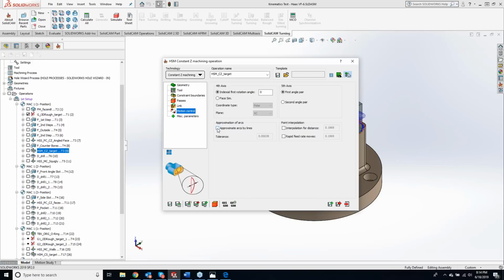So if we turn this on, we're going to get arc segments versus line segments. Kind of like what we're looking at with that iMachining picture, as you're doing surfacing, it's going to try to force arcs in there versus just little tiny line segments going through there. So you definitely have... I think you got that backwards, Kevin. Oh, that one's going to output lines. Oh, yeah, I'm sorry.